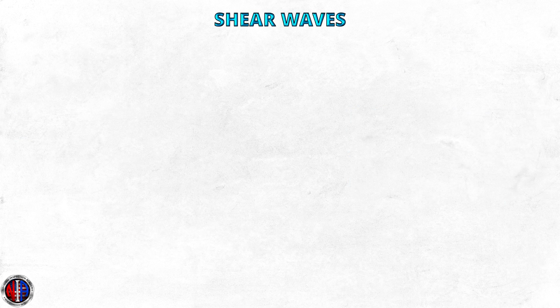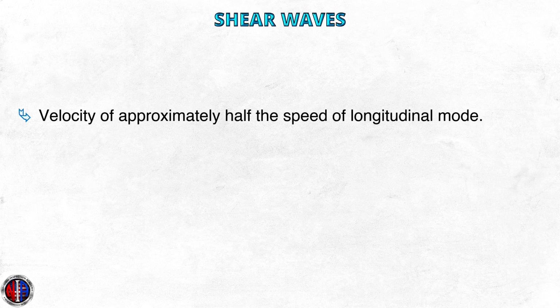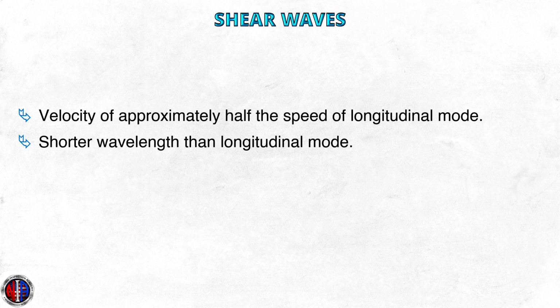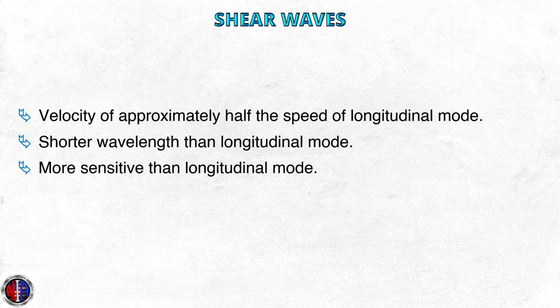Some other specifics to shear waves are, they have a velocity of approximately half the speed of longitudinal mode. They have a shorter wavelength than longitudinal mode. They are more sensitive than the longitudinal mode. They travel only through solids.